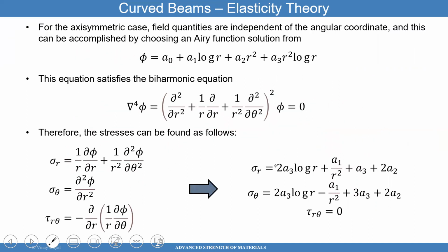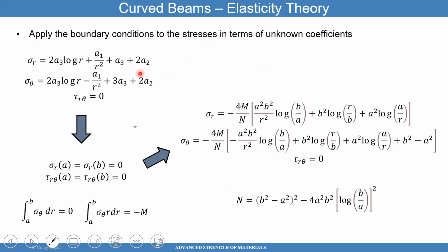I'm not going to make you come up with an Airy stress function. That's not a fair question. But what is a fair question is, that's the Airy stress function. Question number one, does it satisfy the biharmonic equation? Question number two, what are the stresses in terms of the Airy stress function? Question number three, what are the boundary conditions? I'm not going to tell you what the boundary conditions are. Question number four, what are the stresses? Use the boundary conditions to figure out what the stresses are. Are those steps clear? Okay, good.